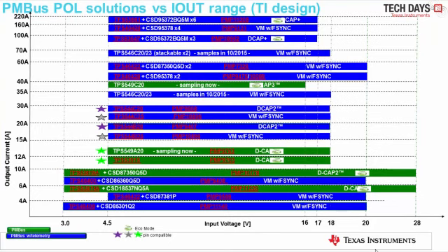This is an XY chart that shows all the PMBus TI designs TI has to offer on our TI Designs webpage. On the x-axis, if you have any input voltage from 3 to 28 volts, we have solutions with PMBus that range from 4 amps that you see on the y-axis, which is the output current, all the way to 20 amps. These are the controllers or buck converters and the corresponding PMP TI designs that you see there.